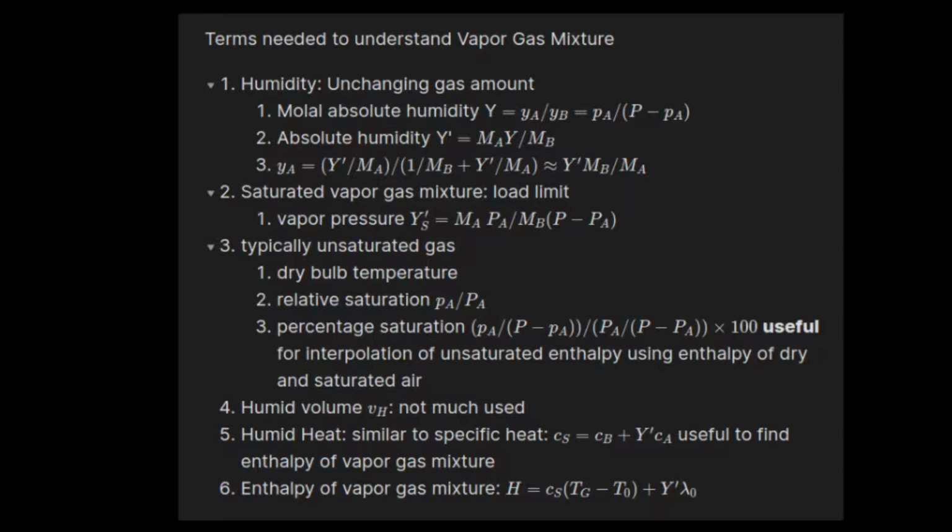Both relative saturation and percentage saturation are useful to identify psychrometric curves. The percentage saturation is useful for interpolation of unsaturated enthalpy using enthalpy of dry and saturated air.